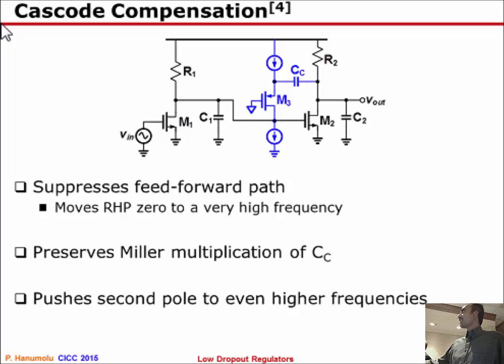Imagine that this M3 transistor is used as a cascode at this point. Imagine M1 is cascoded, and you have access to the source of the cascode device. The capacitor in that virtual, not visible cascode can be used to connect that point. So this branch is sort of reused in this branch. Is that the question?